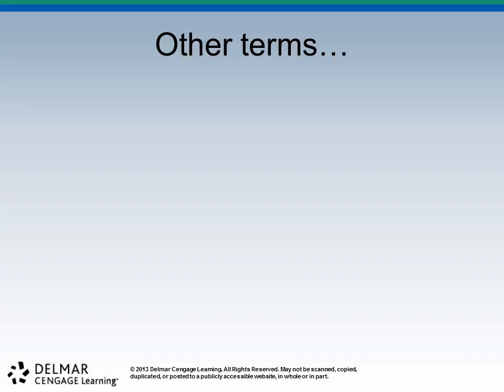And we want to have a current flow like you see in B, where we're not missing any steps, we're not skipping anything. We've got a consistent current flow going through the X-ray tube. Still, this is not the best. And when we get into the next chapter, we'll talk about how we can take single phase full wave rectified circuits and we can flip everything up so that we make, like I said on page 96, three phase rectified units. That's figure 57B. That's much more what we want to see coming through our X-ray tube. What that will mean is that's a constant potential X-ray tube.